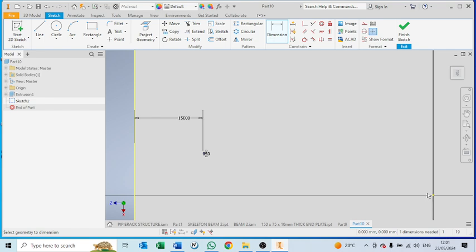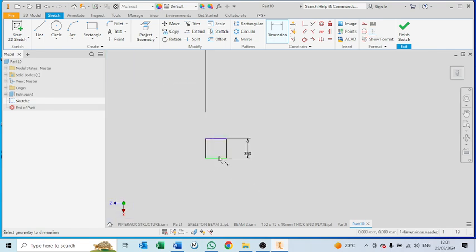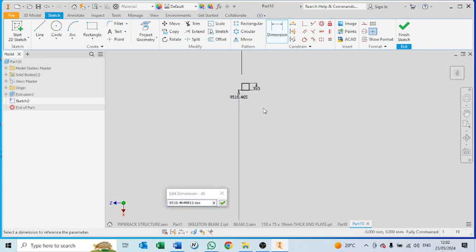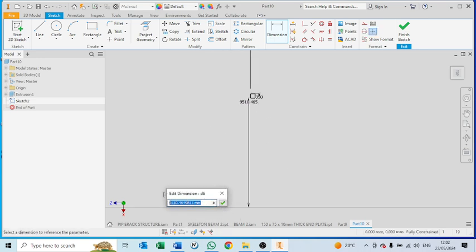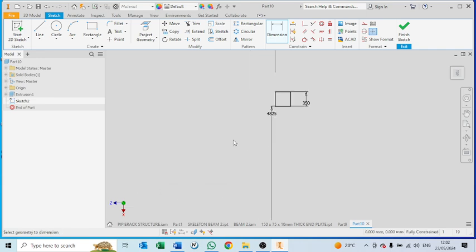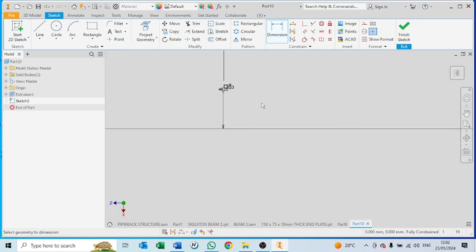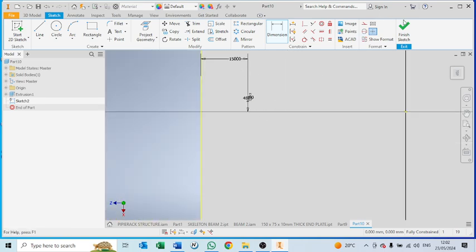Then from the center, because I'm using the centralized concept, because it's 10 meters, the spacing 5,000 minus 350 divided by 2, so that I measure from its center at the end to give me 10 meters. Okay, finish.